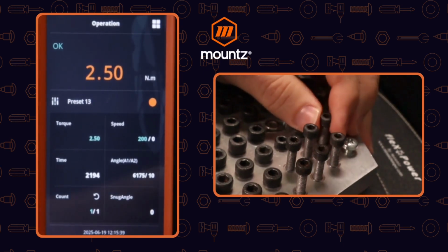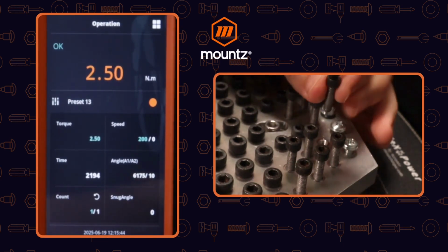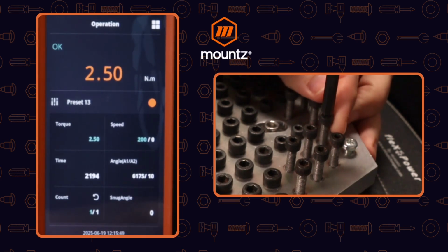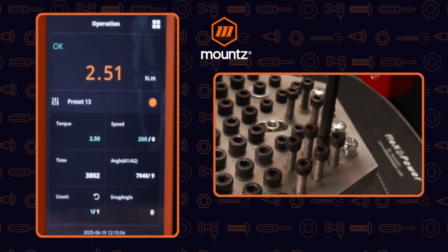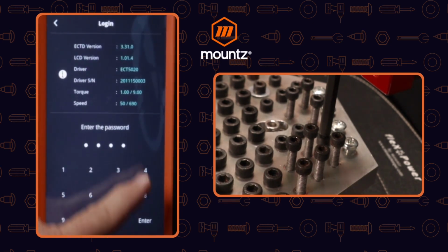Let's use this one here, and I'll take the fastener all the way out so we can show what's happening. So drop that in, and we go in reverse, and then to our soft start, and then finally to our finishing torque and through that RPM. So that's how we can help to mitigate cross-threading, because we want the fastener to get in there correctly.